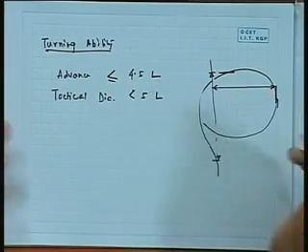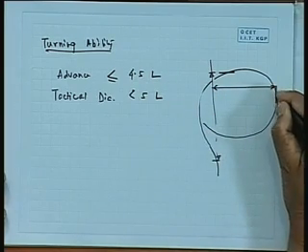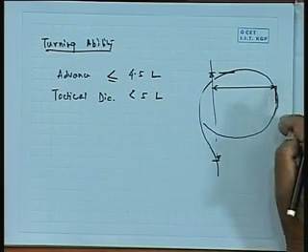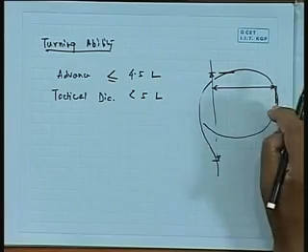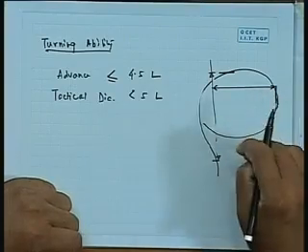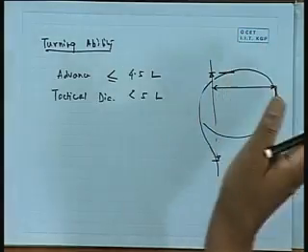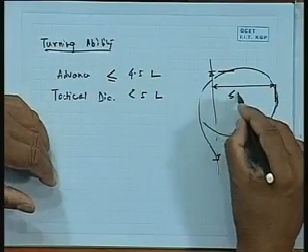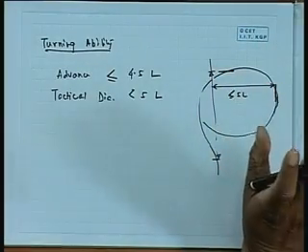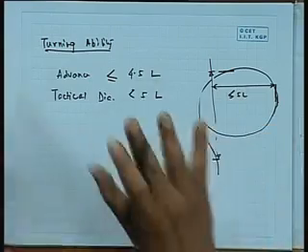You may say, why not the maximum one? Normally they are not doing the maximum one, I don't know for what reason, but maybe it is much easier to measure the heading angle and locate this point when the heading is just 90 degrees, than to pinpoint the location of maximum width. And they seem to be close by. So, this should be less than or equal to 5 L, and this should be less than or equal to 4.5 L. So, it again is very important.